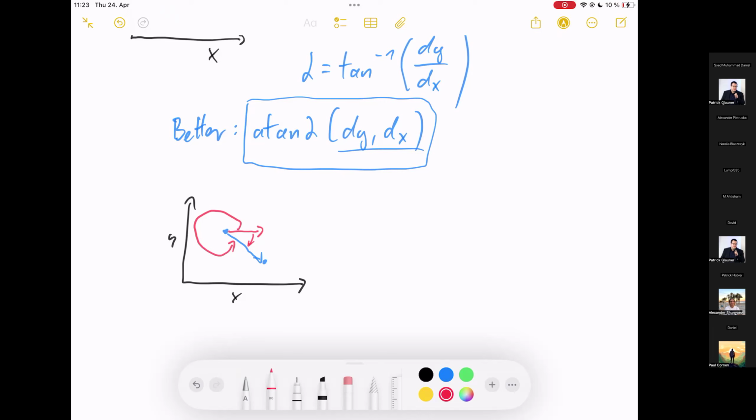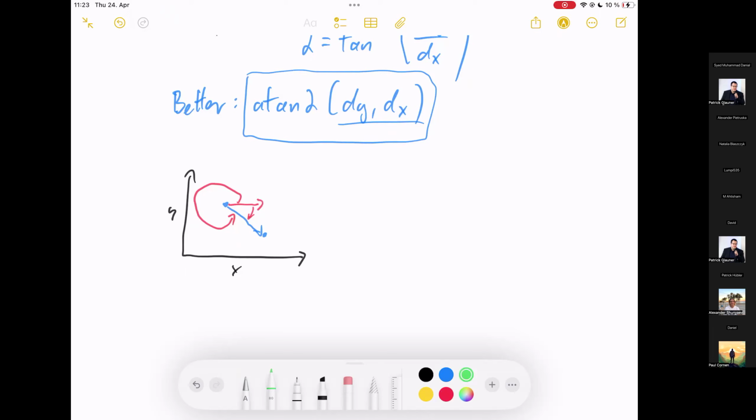So this is something very important. The angle by which you're rotating would be beta. It's our alpha from before, but you subtract your current theta, your current orientation, and this allows us to move the robot as efficiently as possible.